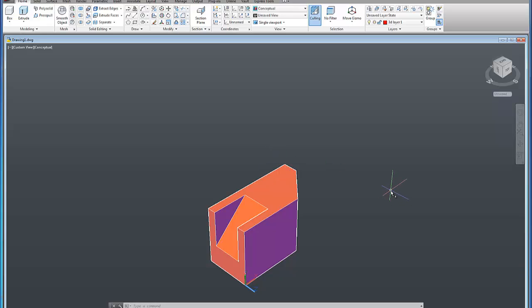Design. And so I need to make sure that I'm looking again, not from the top, but from the side of the object. And I've got that with the X and the Y. I'm looking at the side of the object as my current surface of work, because the X and Y denotes your current surface. Okay, we need to create a shape. In this case, it's going to be a counter bore hole that we're going to put through our object.